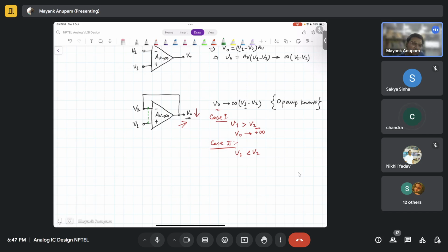It can also happen that two node voltages are equal to each other in some condition, but that cannot be called a virtual short, because in another condition they might not be equal. A direct feedback relation is absolutely essential to call two points a virtual short. Some kind of information exchange has to be there. Only then will one node know where the other node is moving. That is called feedback, information exchange, right?